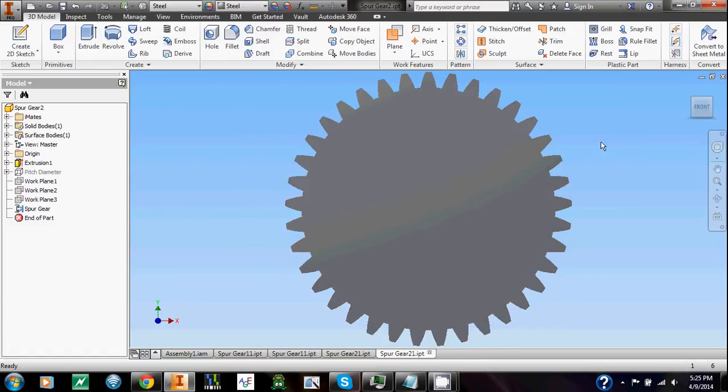And this technique provides a double benefit. From this, I have complete control over the gears individually, which comes in handy when adding things like backlash. It also helps if I ever need these same gears again, I can just go to the known location and grab them instead of repeating the gear generation process multiple times.